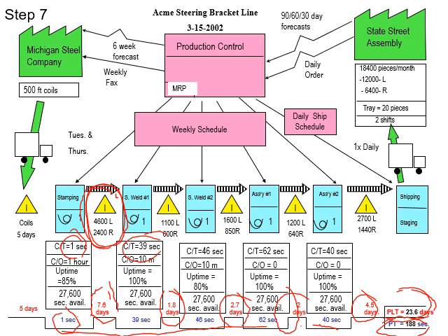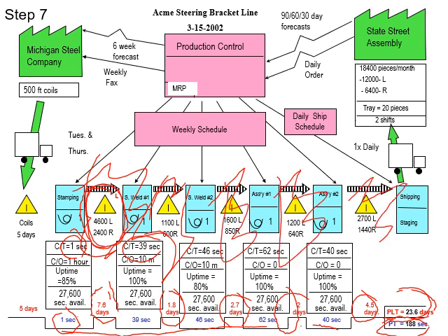This is a huge difference. It means from 23.6 days, the value adding activities amount up to 188 seconds, 3 minutes. And the remaining time is waste, totally waste. If you have a look here, this is a huge waste. This is another waste. This is another waste. Another waste. If you have a look here, this is a waste, 85%. It's just working for 85%.